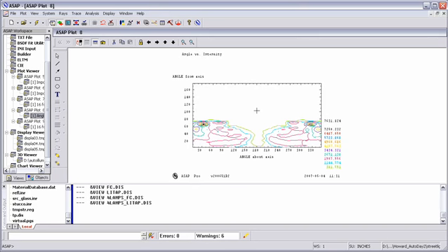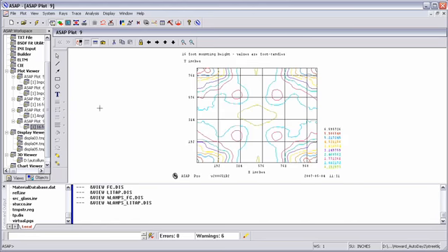And then we've got a plot of what we call the type C photometry of the lamp. For people that are familiar with that, this would be as though we'd photometered the lamp in the lab. And this particular lamp was designed to be a full cutoff lamp, and this plot is showing us that we do not have any uplight, and that we are meeting the full cutoff criteria. And then this is also an isocontour plot of 4 lamps positioned at each corner, so we can see the illuminance that we would have if we had used 4 of these lamps to light a roadway section.